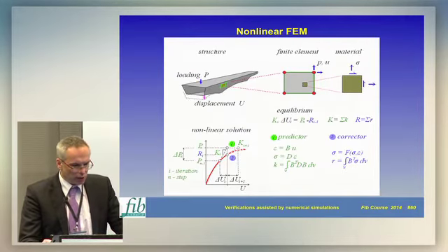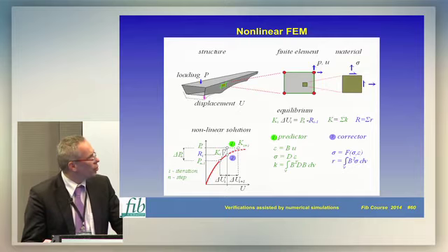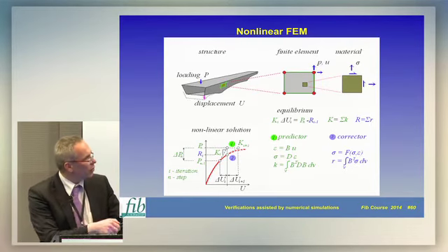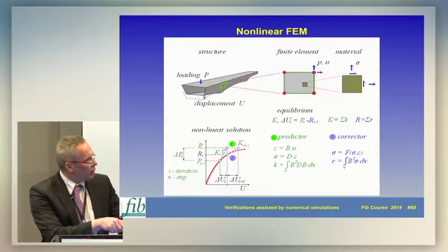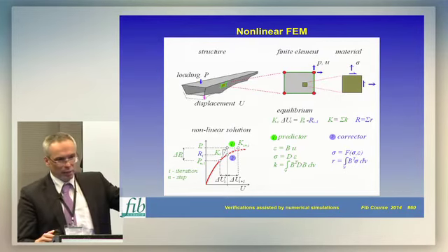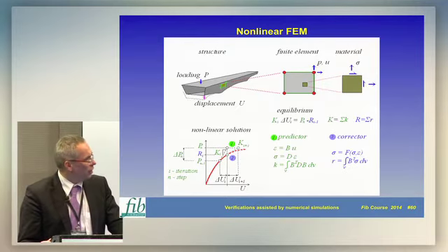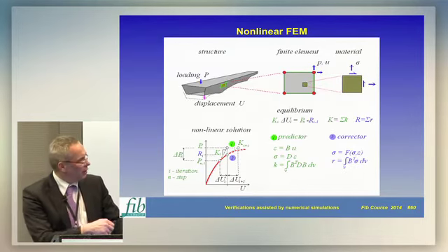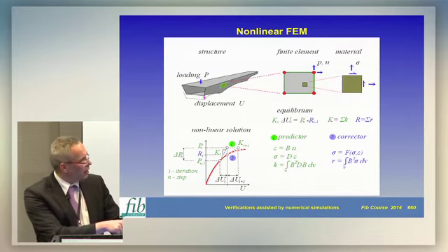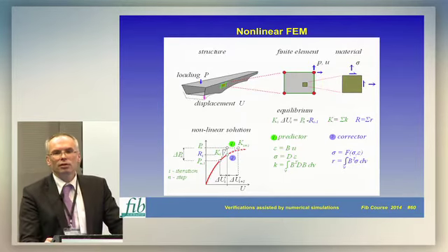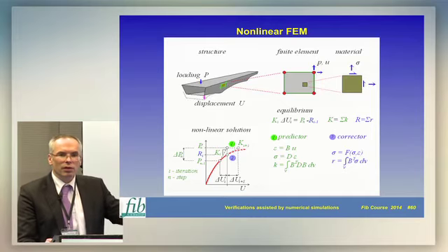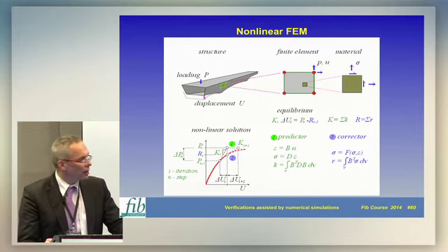So when using nonlinear analysis, the typical situation is that most softwares introduce some advanced material models, which divide the nonlinear analysis into an incremental and iterative process. In each increment there are iterations. First there is an elastic predictor assuming elastic behavior, and then the stresses throughout the structure are checked with respect to the criteria and are reduced